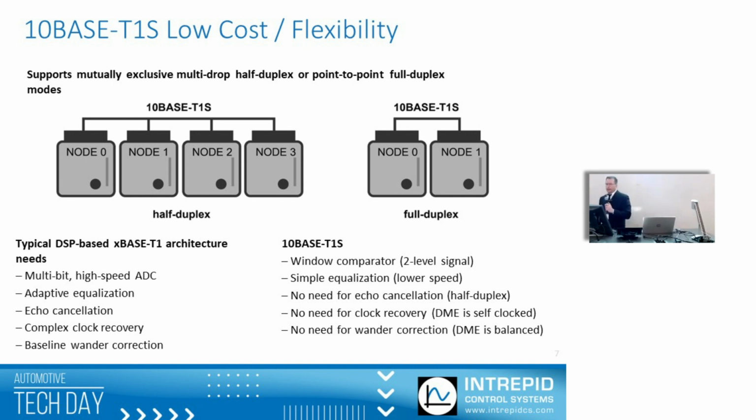Now 10BASE-T1S, as I mentioned, its primary purpose is to be a multi-drop or bus topology so that it can compete with CAN-FD and FlexRay. But it is possible to run it in full duplex, point to point, just like other networks. We should mention that point.